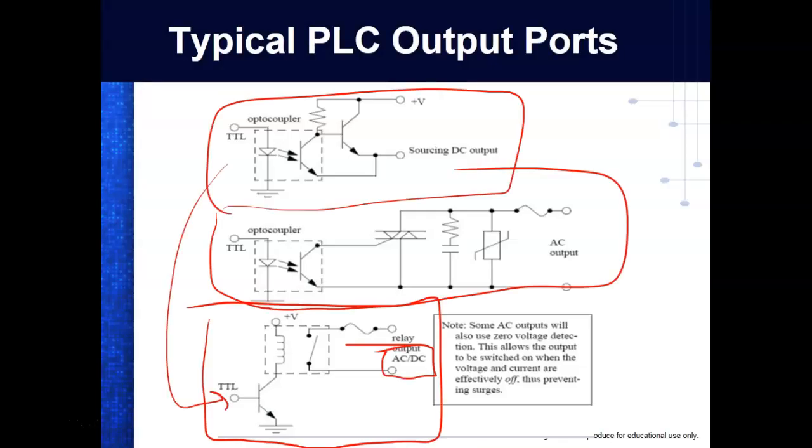The three types of outputs, we need to really know that because we buy the PLC. One of the things we specify is outputs. So if I came up here and looked at these outputs, if I looked at the module, it says they are sinking. The input says sinking, and the output says they're sourcing. So we need to understand what that means. Did y'all see that? We know that.